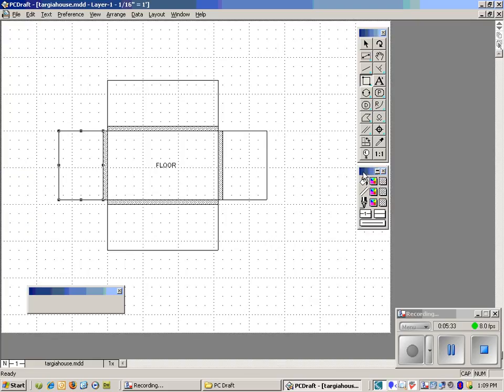And if you look at step number 13, it says now you must construct your roof pitch. Select the 45-degree line tool and draw two lines from the long end of your house that will slightly cross over each other. So I'm going to go to my line tool and I need the 45-degree line. So I'm going to hold this down and select 45.